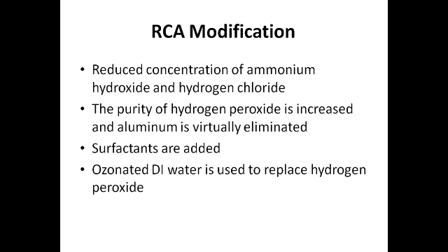There have been a lot of RCA modifications. The chemical concentrations have been reduced. The purity of hydrogen peroxide is increased, so there is no metal, especially aluminum. The other modifications are surfactants and ozonated DI water.